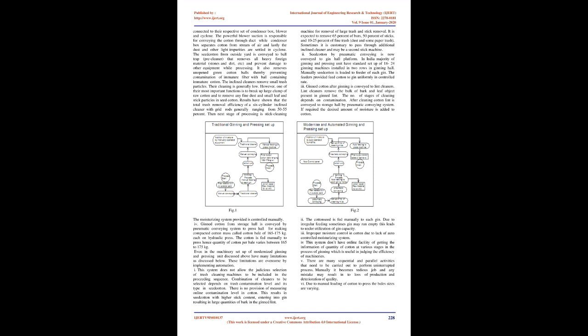1. The seed cotton from the outside yard is conveyed to the ball trap, a pre-cleaner that removes all heavy foreign material, stones and dirt, etc., and prevents damage to other equipment while processing. It also removes unopened green cotton balls, thereby preventing contamination of mature fiber with balls containing immature cotton.